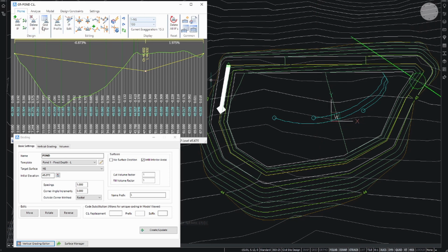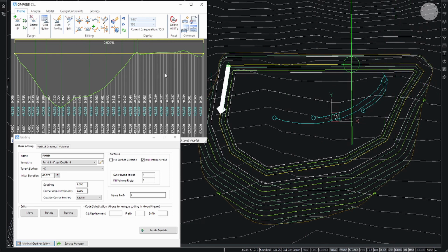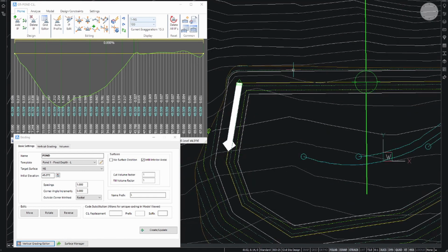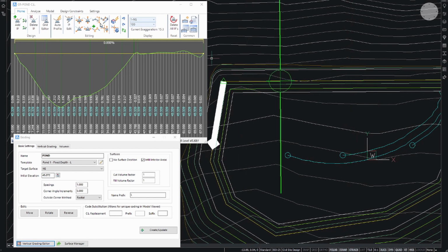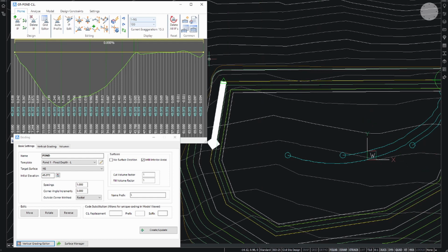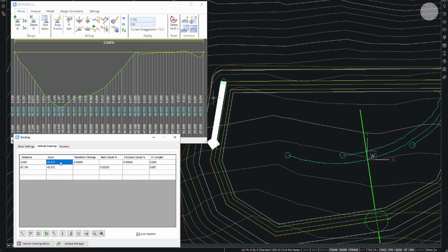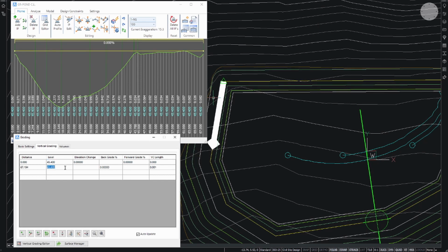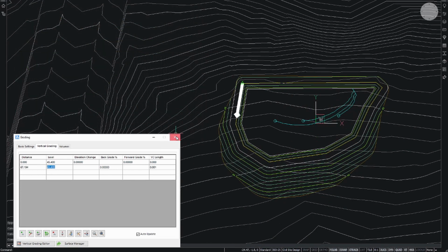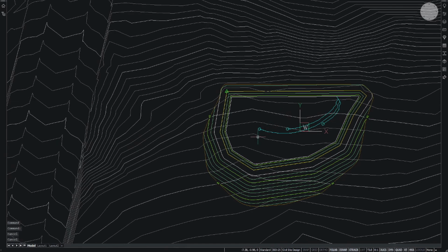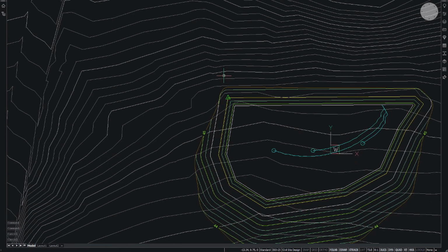In this case, the pond to begin with is reasonably simple. All we want to do is minimize the amount of fill that's going to happen in the northern end. So we would position these elevations to work through that. So that's close to what we want. If we look at our tab here, we can see we're on 45.372. So I'll make that 45.4. So we got a nice even value. So that's good enough for what we need here for a starting point. We can always change it afterwards and do more work with it, but I'm happy with that to begin with.